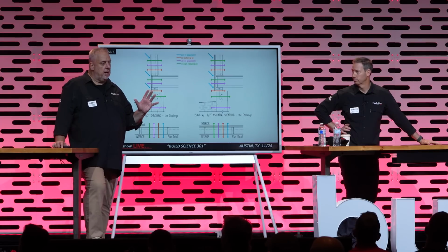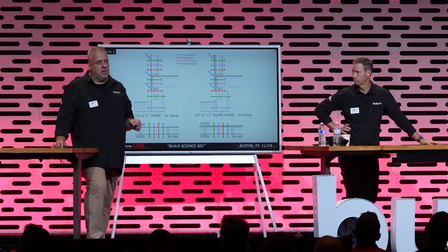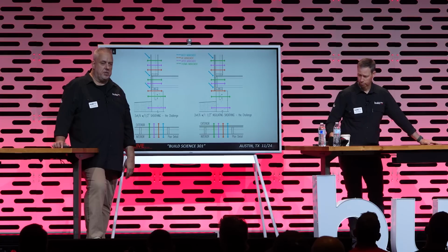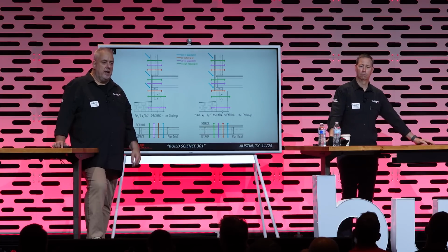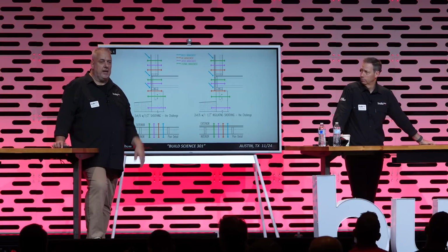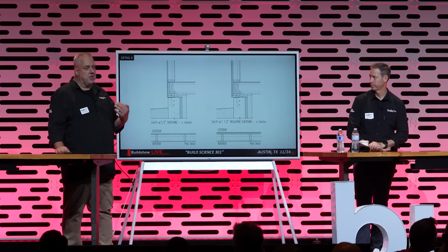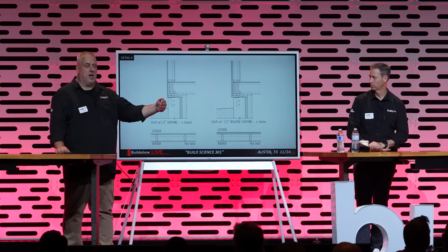And if you understand, if we did a full section of the house, this is an area that has some of the highest negative pressure on the house, right? The house is basically sucking on the outside, and it's trying to get stuff in. So let's look at it. And in fact, our standard detail is to put 4 inches of closed cell in there. And you know, whether you're an advocate of foam or not, our position in our office is always the right material for the right job.